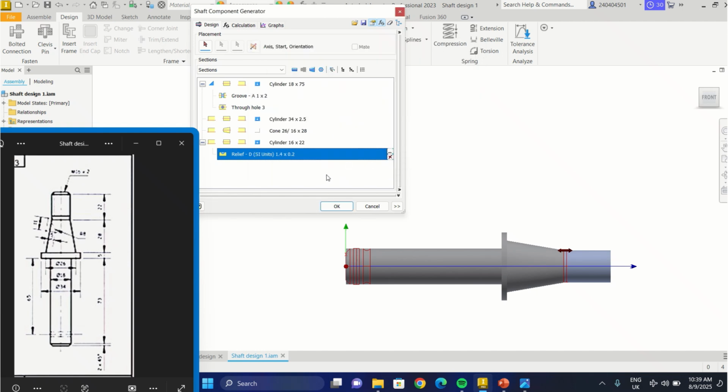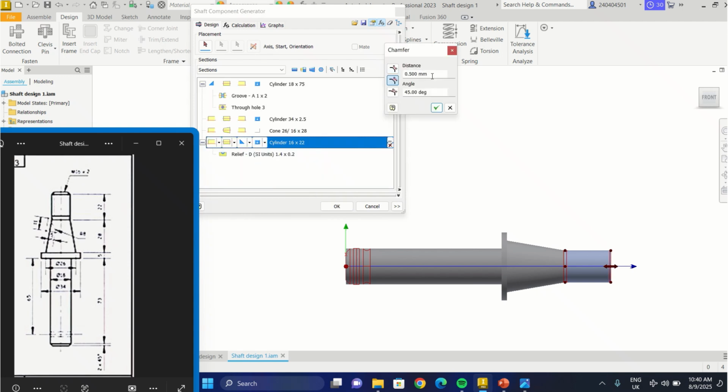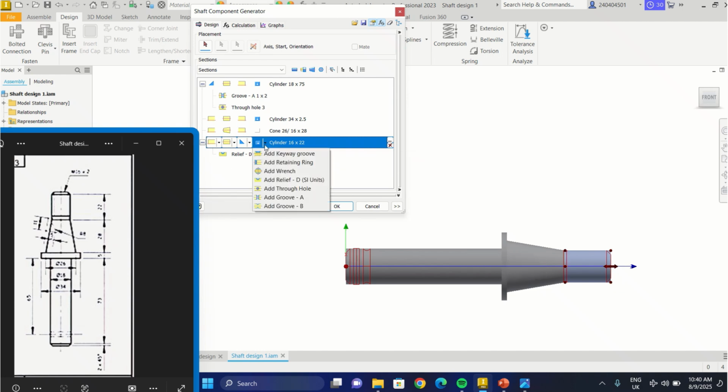Then at the same time we have a chamfer on the other end. Let me chamfer before I thread. So I'm going to introduce here a chamfer, and I'm using 2 by 45 degree. Notice it has introduced a shaft at the end also. And the last thing that it has is a thread. So I'm going to introduce a thread to it.